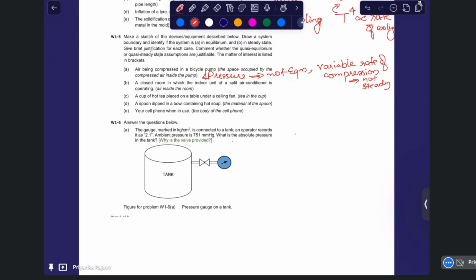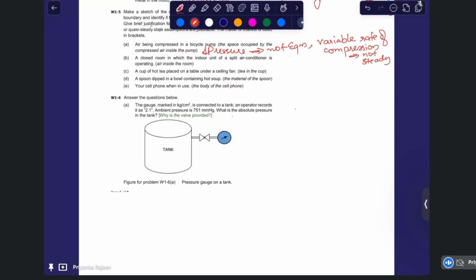So that is steady state, but not in thermodynamic equilibrium because there is mass inflow and outflow. Even though thermal equilibrium is there, mechanical equilibrium may not be there. And with coolants working, there won't be chemical equilibrium either. So there won't be thermodynamic equilibrium. So it is not in equilibrium.